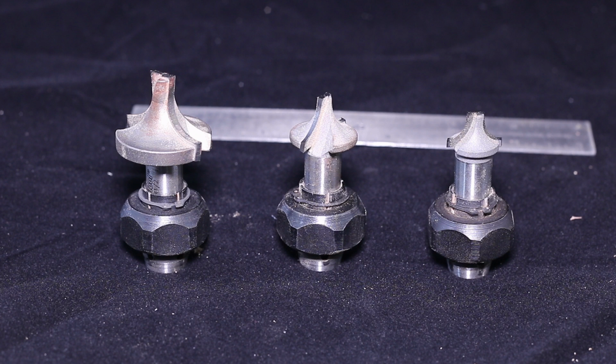Okay, these are from Magnate. They are a set of 3 roundover bits. Most woodworkers know what roundover bits are. If you notice, these don't have a bearing. They're called Plunge roundover bits. If your machine is able to take a 1/2-inch collet, these are great to have for edges in doing plaques and things of that nature. They're also good for spindle work to make beads and coves if you have a lathe attachment on your CNC. And so for me, must have Plunge roundover bits from Magnate.